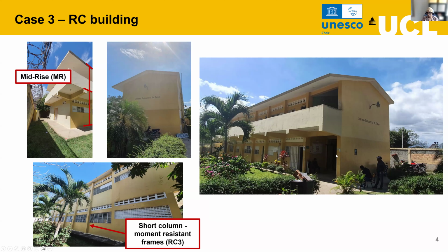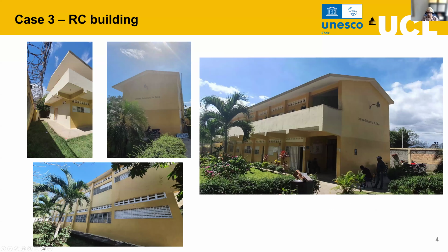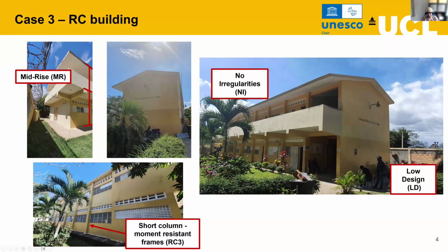With the features given for the seismic design features and the age of construction, we can assess that this has a low seismic design level. This doesn't seem to have any irregularities. It's a rectangular plan building, with no structural irregularities in the vertical direction. We can see that the span is less than 6 meters between the frames, and hence it can be called a short span structure.